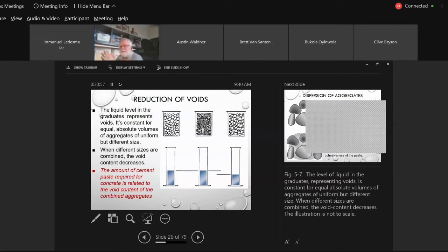We've got aggregates. We also have cement. We also have water, and we have admixtures. So in other words, we're going to make up a paste of cement and the fines from the aggregate. I had mentioned earlier that we want a coating of aggregate around it. In other words, you want that paste to coat each individual aggregate. And you want the aggregates clean for the simple reason you need good bond.